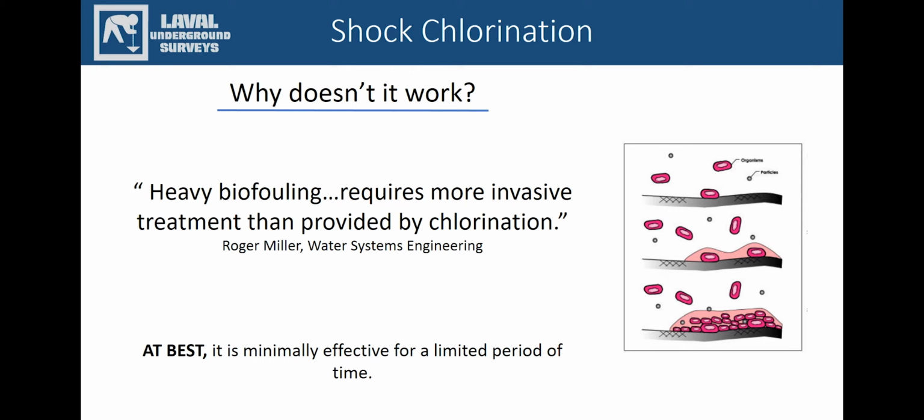One of the main reasons people use chlorine on biofilms is because it's so cheap. This is true. You can get chlorine at a fraction of the cost of specialty chemicals, but the issue is, what will it cost in the long run? Using chlorine to treat biofouling might give you an initial clean, but over time it'll stop working and it will cause more problems than it helps. This leads to an expensive fix later on.